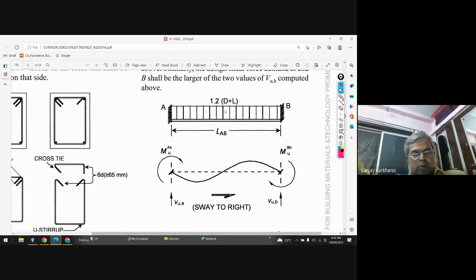Analysis में आपने वो सब निकाला, वो ETABS में मॉडल बनाया, STAAD में मॉडल बनाया, फोर्सेस निकाले, उसका 1.5 टाइम्स डेड लोड प्लस 1.5 टाइम्स लाइव लोड, वो सब निकाला, फिर वेरियस लोड कॉम्बिनेशंस जो हमने देखे वो सब निकाला. That is the analysis. Here we are checking the capacity. What is the maximum capacity, right? And we are taking care that the analysis results are showing lesser loads than the capacity.